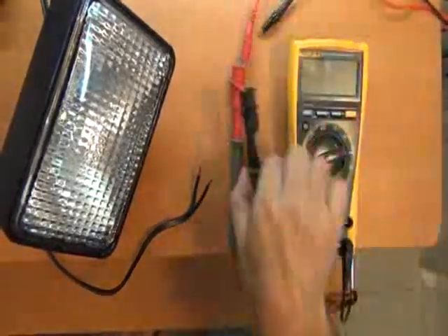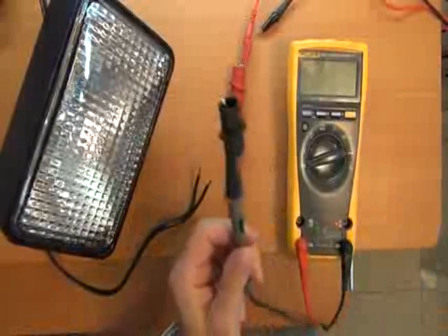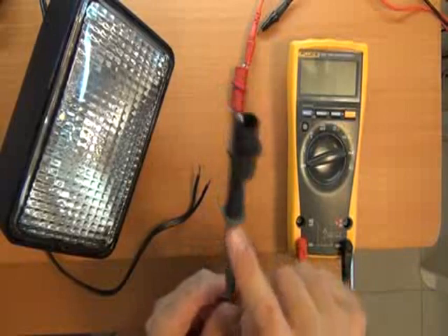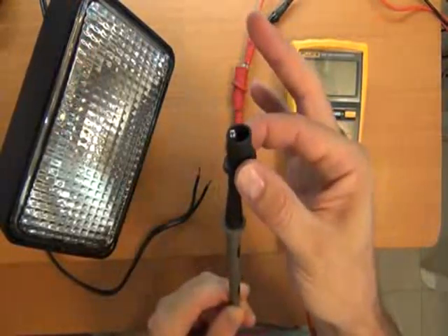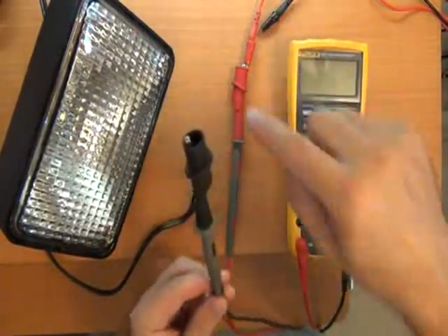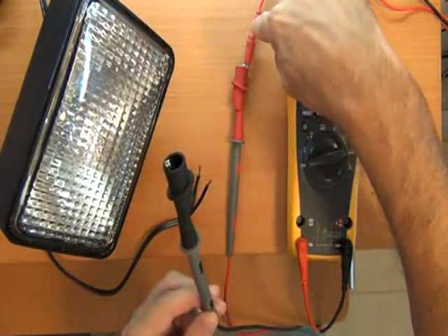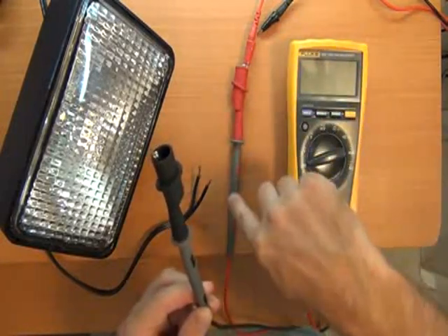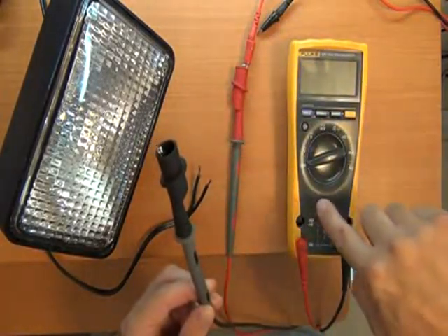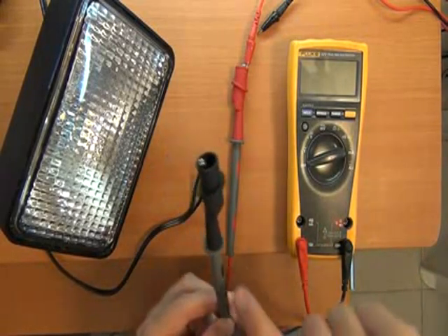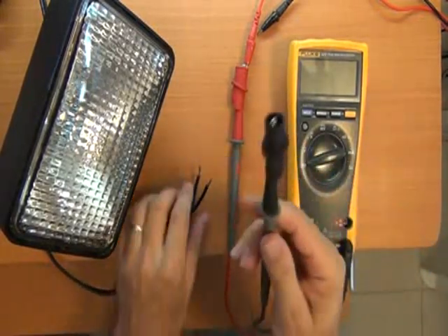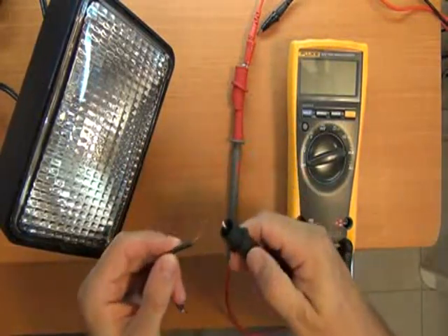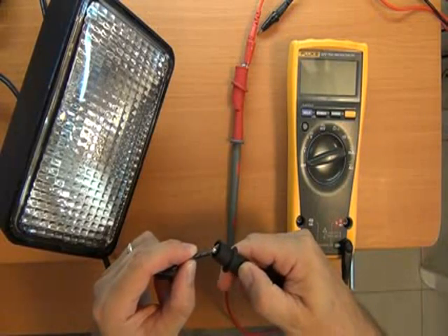Then in essence, and this is where it gets a little bit confusing, your black probe on your multimeter isn't acting as a negative this time. This is one line of the circuit, the positive line of the circuit, and I'm going to show you in a diagram, but this positive line comes round through your multimeter. It's still positive, it comes out here, so this needs to go to the positive connection of the load that you're trying to feed electricity to, or your DC voltage to.